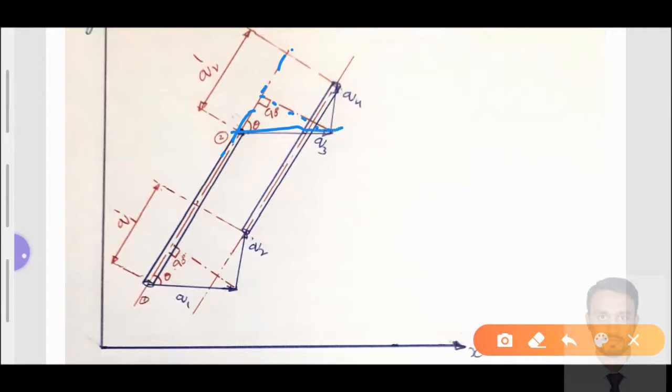This is the line, q3 direction is parallel to the x-axis, and I will draw the perpendicular line from here. We can see this 90-degree line with respect to the axis of the bar element, from the initial position towards the displacement of this axis. See here, to this point we have drawn it, and that is 90 degrees. It makes an angle of theta. Similarly, we have the 90-degree axis here, so this is the theta value, right?